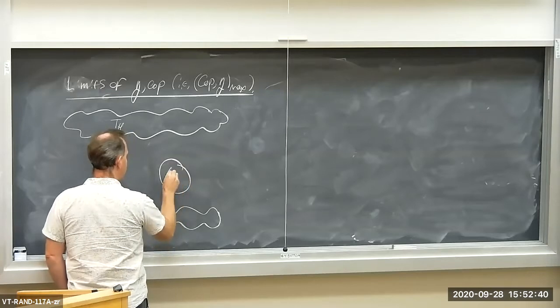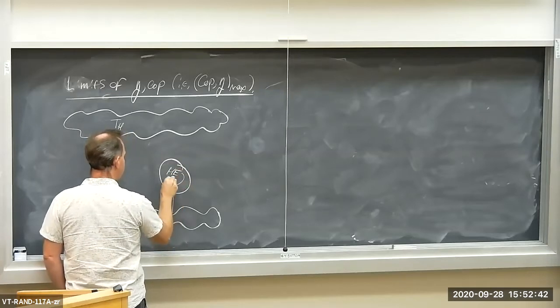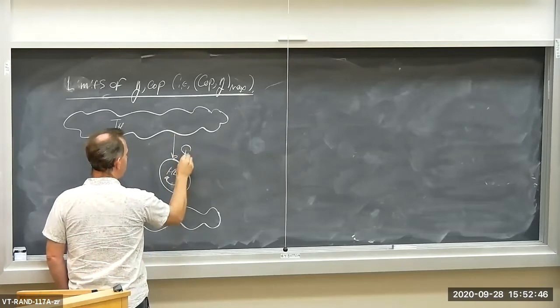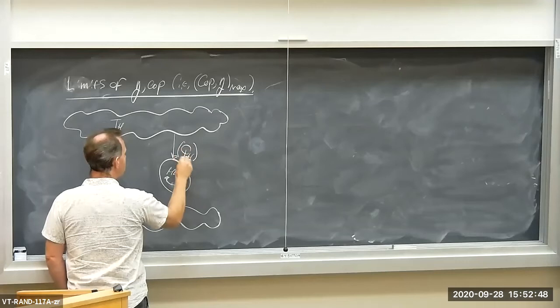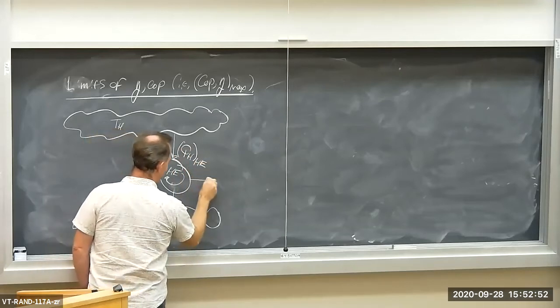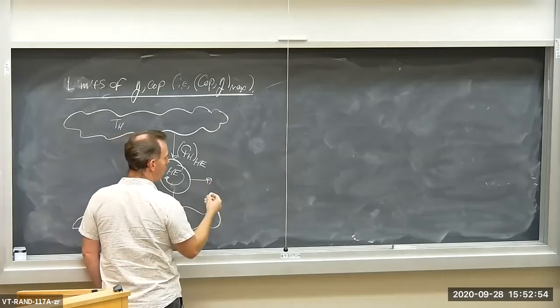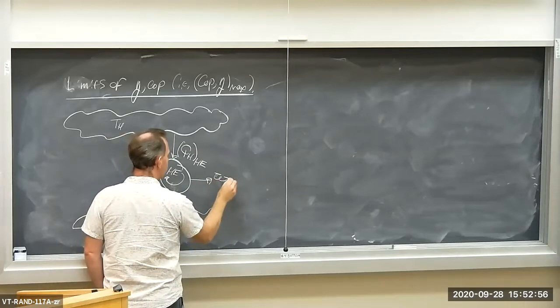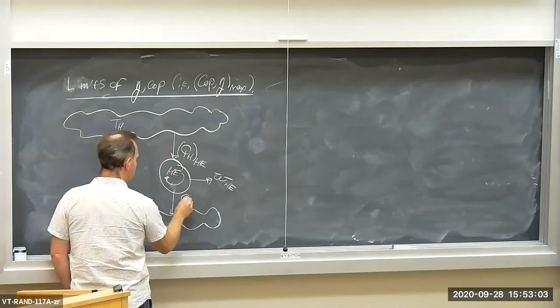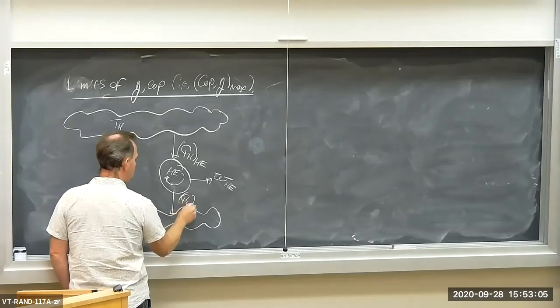So here's a heat engine, and it's working in a cycle. Now, this heat engine receives a certain amount of heat, QH heat engine. It takes some of that heat and produces work. And the remaining energy, what's left over, it rejects to the low temperature reservoir, QL heat engine.